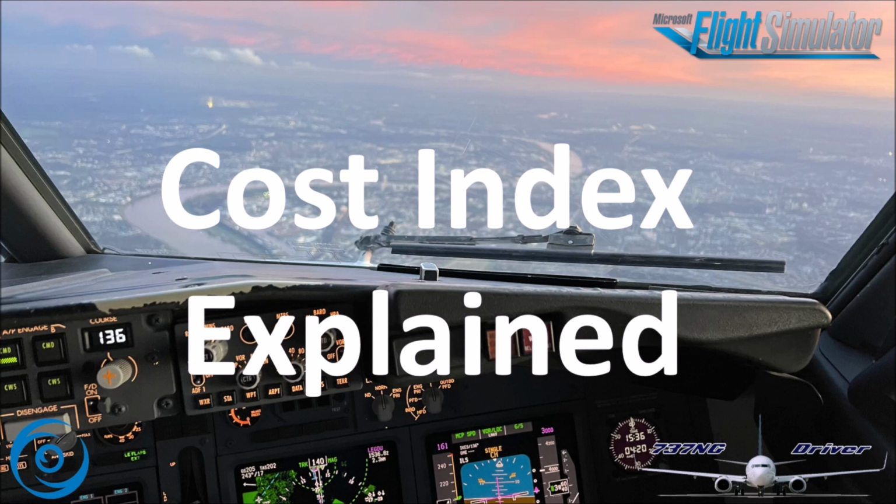Now, things aren't quite that easy, however. Let's have a look at the typical operating ranges of cost indexes. In our 757 example, Boeing uses the number 70. Now, since this is a 737 based channel, I'll bring in some practical experience here. So for 737s typical cost indexes are in the region between 10 and 30. And to illustrate the same with the Boeing example, however, we'll use cost index 70 as a typical example here.